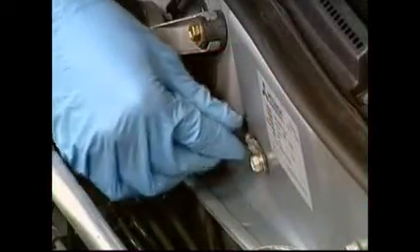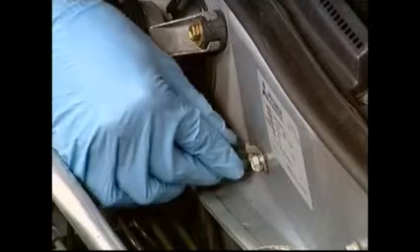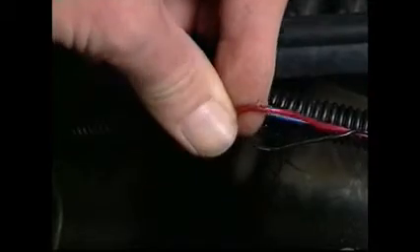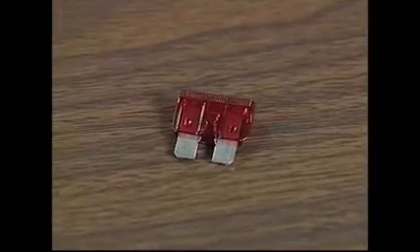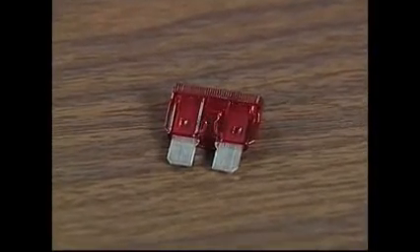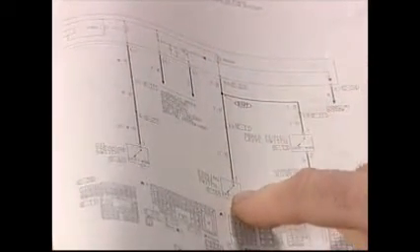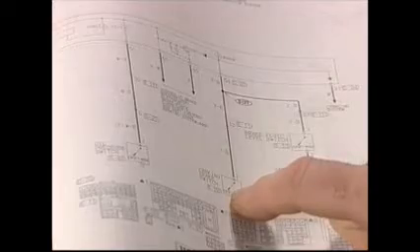Increasing resistance in a circuit through loose connections or corrosion will cause a reduced current flow. Decreasing resistance in a circuit by providing an alternate path to ground will result in an increased flow that will melt a fuse or trip a circuit breaker. Understanding Ohm's law and the relationship of current flow to resistance is one of the most important tools a diagnostic technician has in troubleshooting electrical systems.